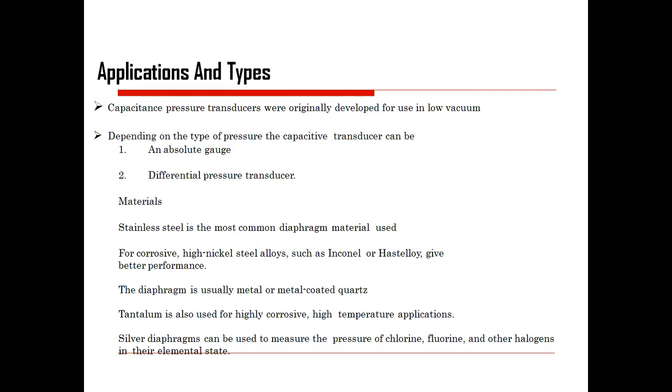Then Inconel or Hastelloy provide much more improved performance while designing the diaphragm for a capacitive type of transducer.